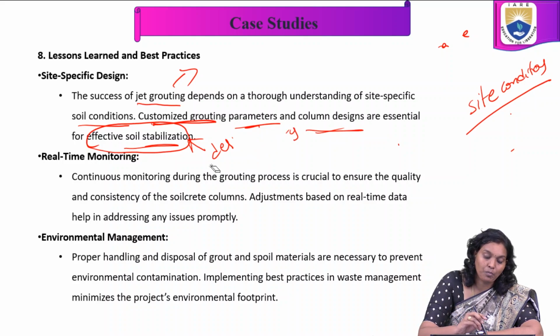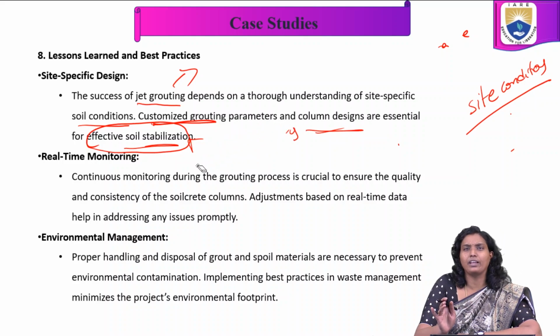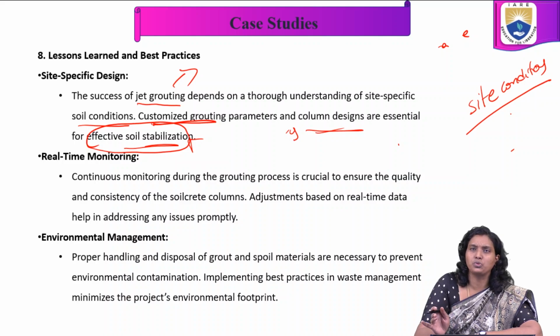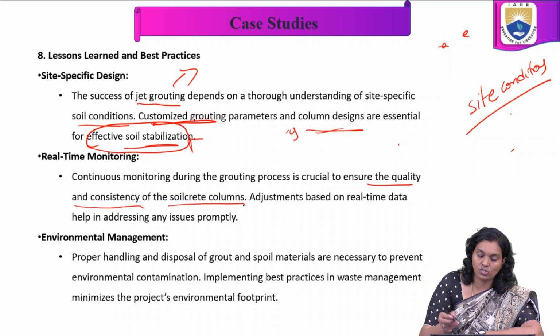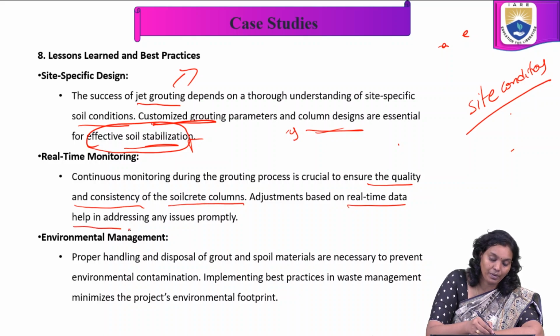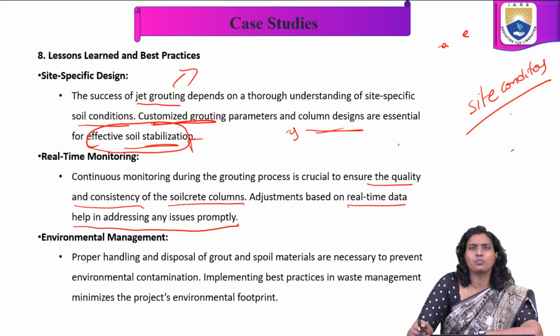And real-time monitoring: continuous monitoring during the grouting process is crucial to ensure the quality and consistency of the soil-crete columns. Adjustments based on real-time data help in addressing any issues promptly. Once we understand the various case studies and best practices for those case studies, this real-time monitoring is also understood very quickly.